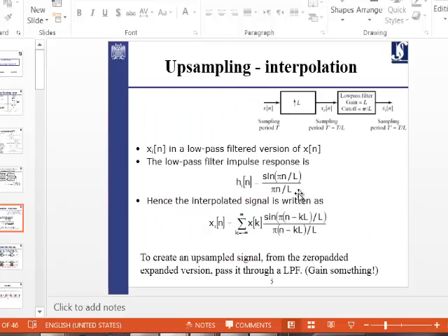We already talked about changing the sampling rate through two concepts, upsampling and downsampling. And we already studied how they affect the spectrum of the signal. With downsampling, the spectrum gets wider, which brings the danger of overlapping of consecutive patterns from the original period and the neighboring periods. If that overlapping happens, it means aliasing, and aliasing means losing information.